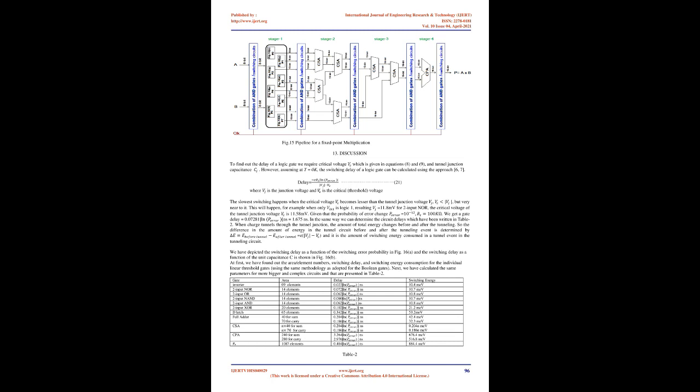Now, after the addition of three binary numbers A, B and C, we obtain the arithmetic sum. The sum is obtained by bitwise addition of the binary numbers, and the carry is shown in Fig 12, C. The operation of CSA is presented in Fig 12, D, and its symbol is given in Fig 12, E. Fig. 12, A, sum, B, carry, C, bitwise sum, D, n-bit CSA and, E, symbol of CSA.